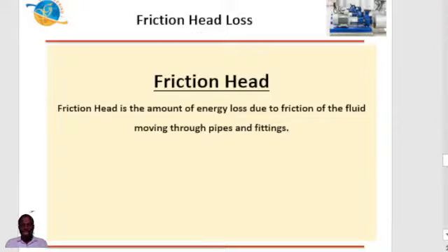You are introducing friction into the system as the liquid is traveling along the pipes from the suction tank to the pump, and at the same time from the pump into the discharge pipe. You are introducing friction with the increasing flow rates.